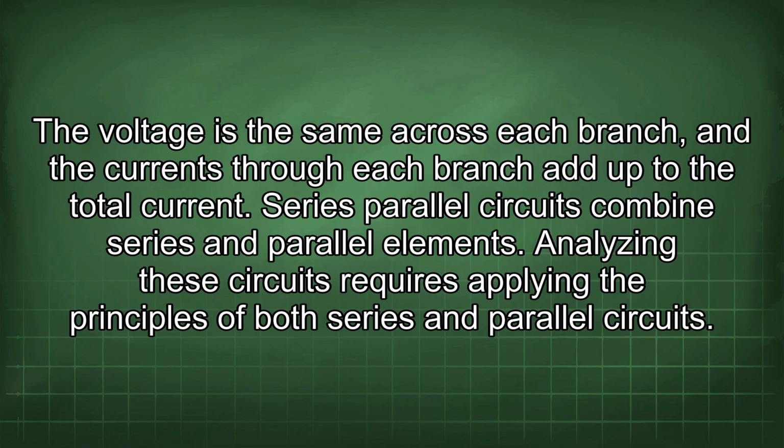The voltage is the same across each branch, and the currents through each branch add up to the total current. Series parallel circuits combine series and parallel elements. Analyzing these circuits requires applying the principles of both series and parallel circuits.